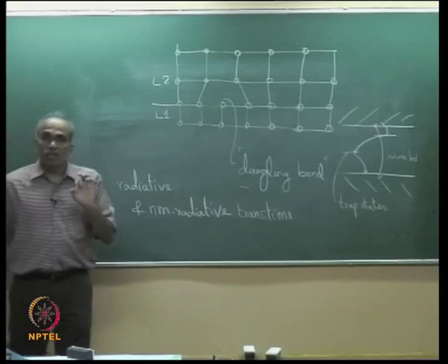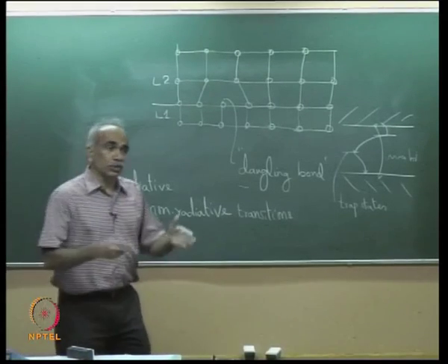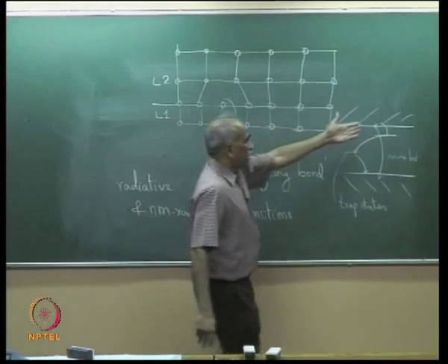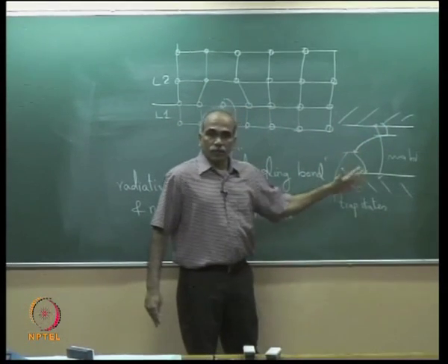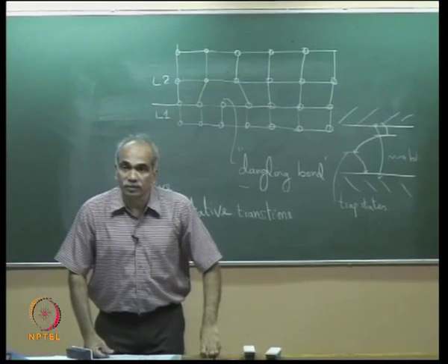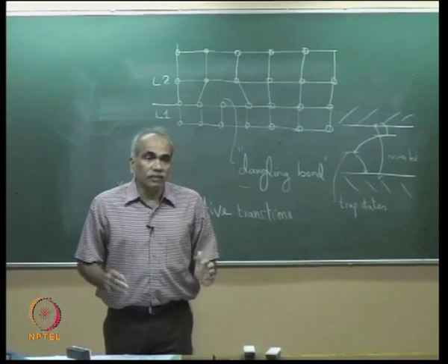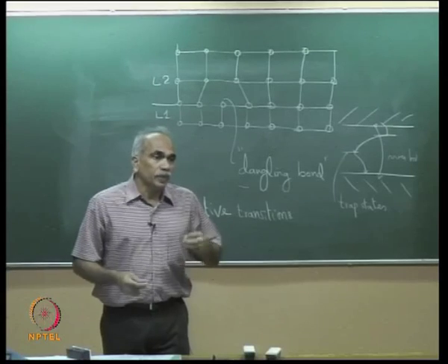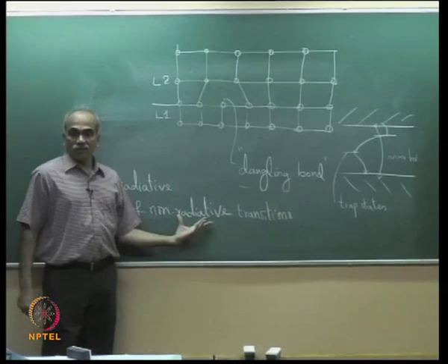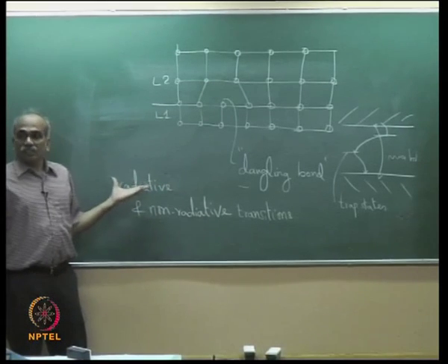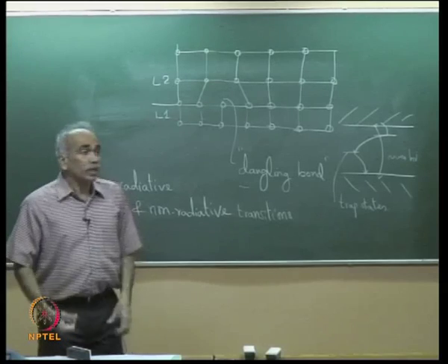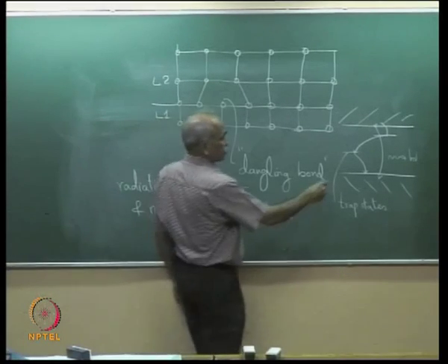In electronics, most of the time we just have to pass current. It doesn't matter whether it is going through non-radiative or radiative recombination; recombinations are taking place, which means current is flowing through the device. But in optoelectronic devices, it's very important that non-radiative transitions are minimized. Primarily, the transitions should take place radiatively so that emission or absorption of a photon is involved.